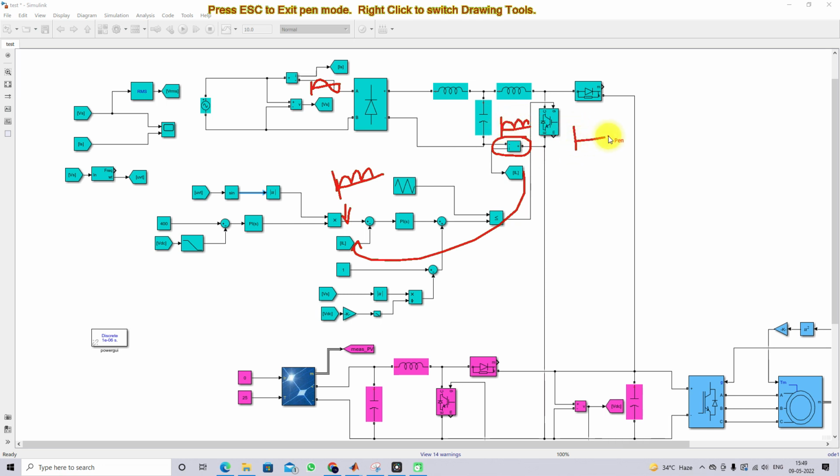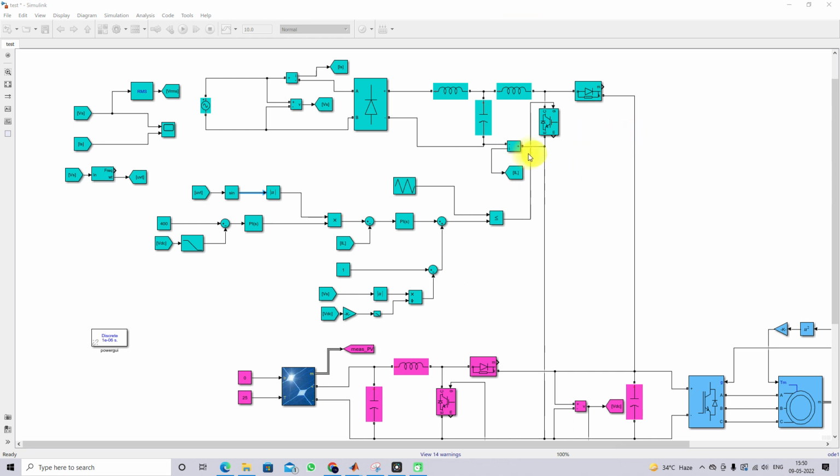When you do not use this power factor converter, the current shows this kind of waveform. It is not the rectifier output, so there is some distortion in the system. Here we are going to make this current sinusoidal, in line with the rectifier output concept. For that, we compare this reference current with this current.